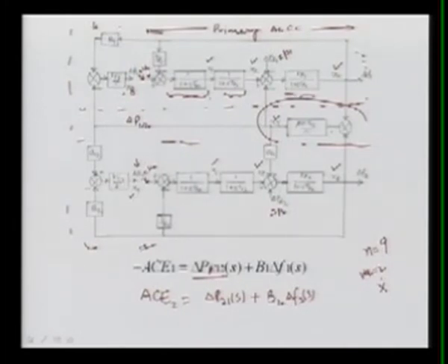So what we are going to do, we are going to write x1, which will be nothing but the input coming to this transfer function. x3 is the state which is coming here, so we are getting minus x3 by r1. Why minus? Because the minus sign is there, plus your input u1 here, multiplied by this transfer function, which is nothing but 1 over 1 plus sTg1. From here we can easily write this expression.